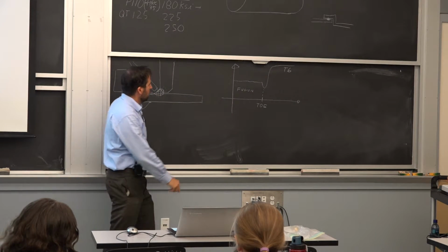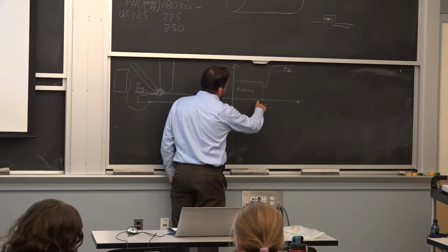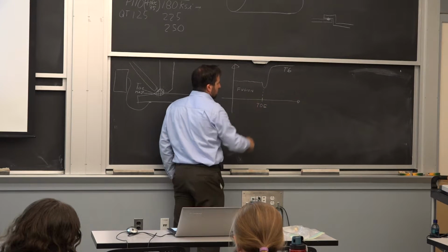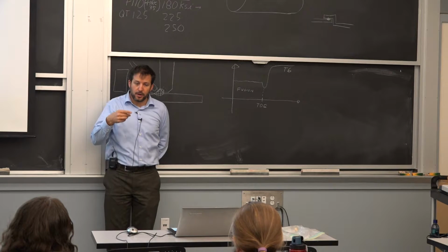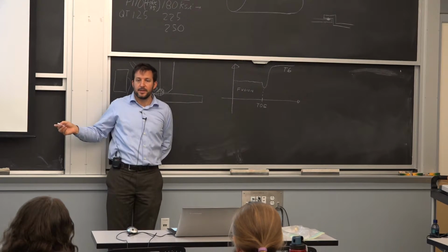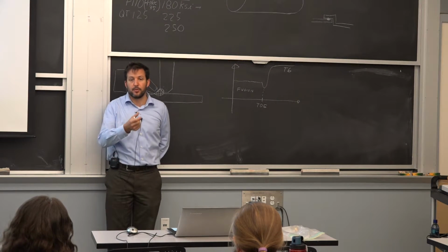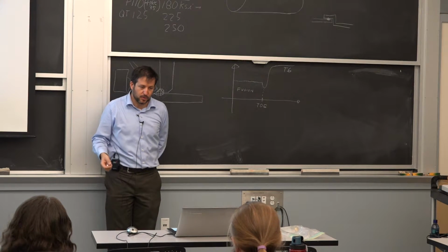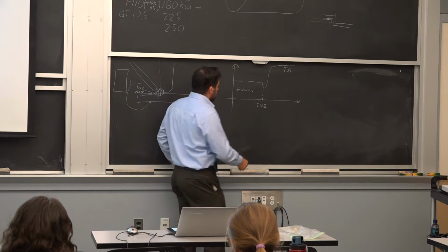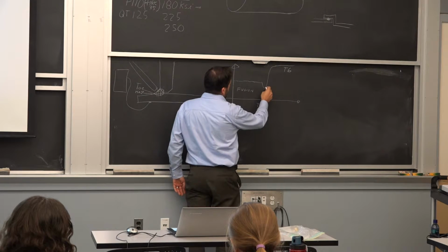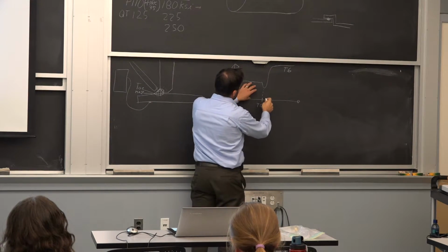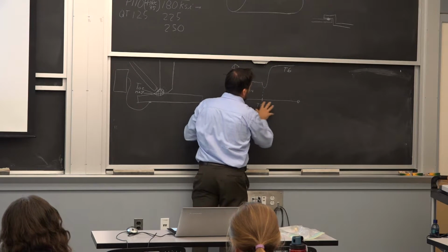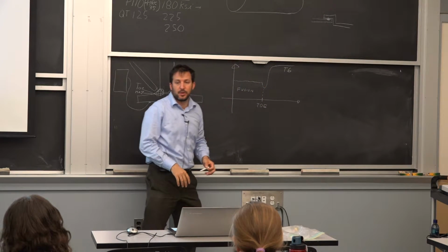So we got this because right next to the fusion, the material got to the melting point. And that's where all these little precipitates go back into solution pretty quickly. It's very hot. There's no problem for it. Now, our temperature profile here is going down, but as soon as you stop the fusion, all the heat goes into the base material.